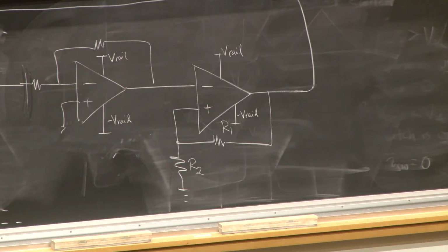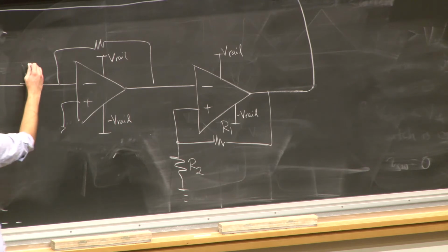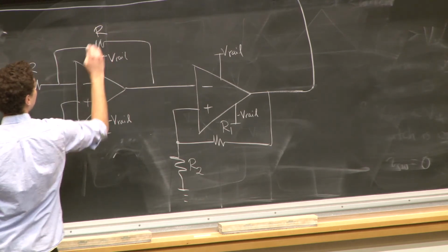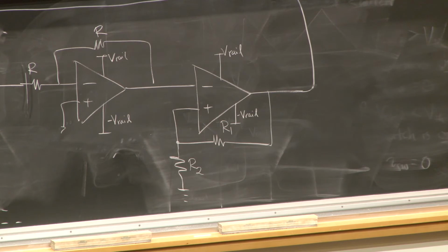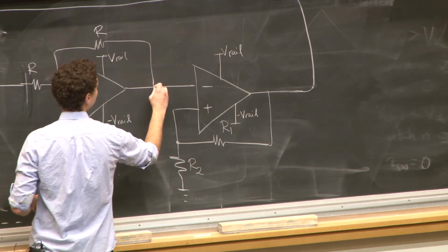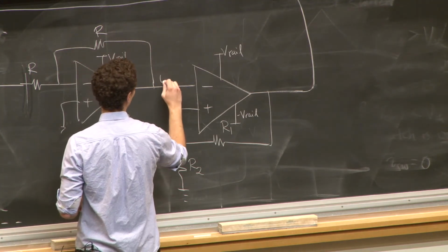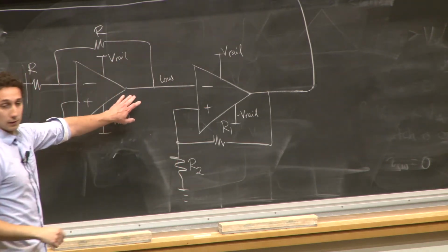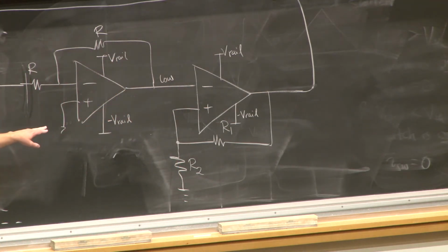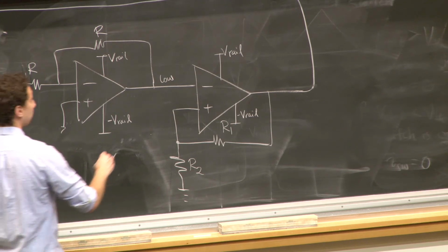Now what sets the condition for when my voltage switches? So here we've got R and R, let's say. What sets that condition? R2 over R1 plus R2. So suppose that we start with a low voltage at the negative terminal of this comparator, and it's going up, increasing.